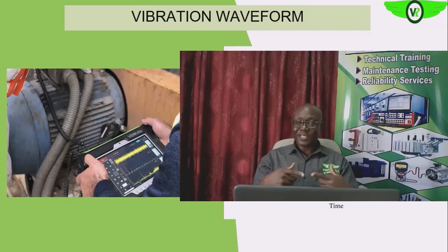So if we have 8 blades, the contribution of the impeller into the overall vibration will be seen at 8 times the speed, or the fundamental frequency of operation, of that particular pump or electric motor, if it is not attached to a gearbox. Are we getting it?